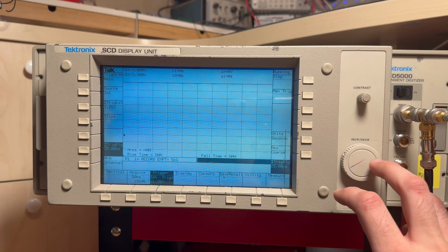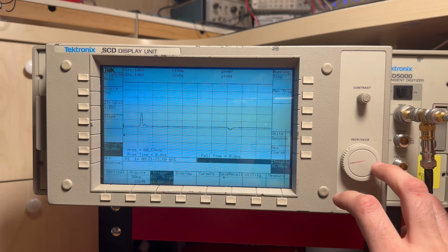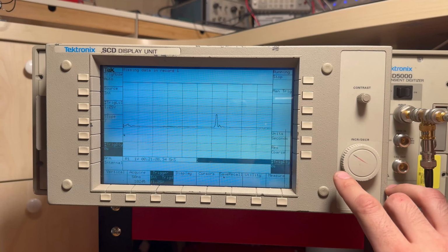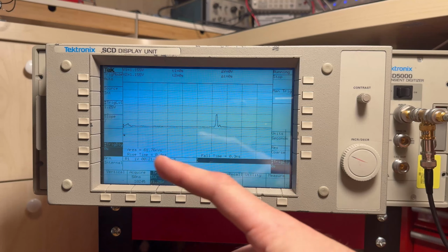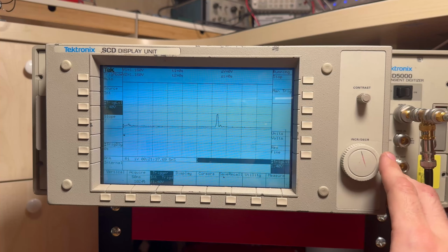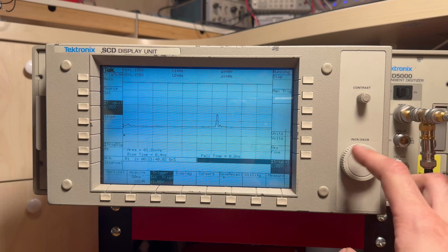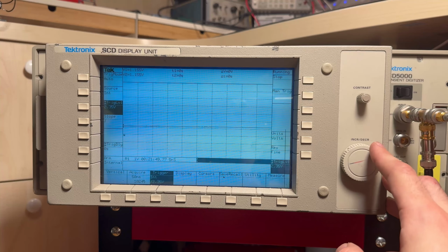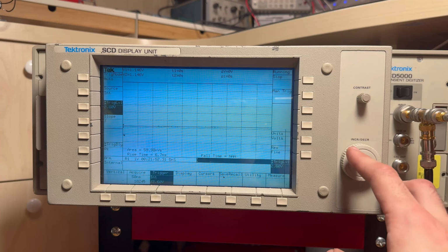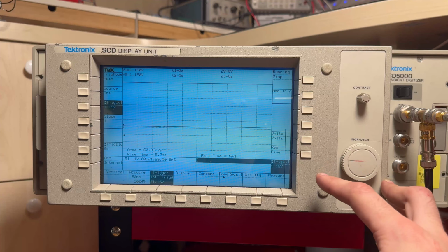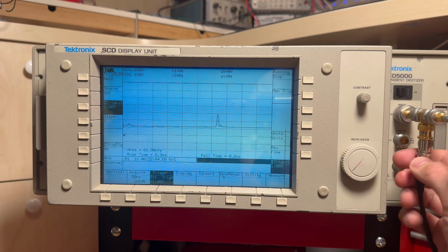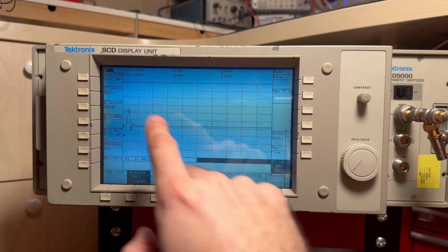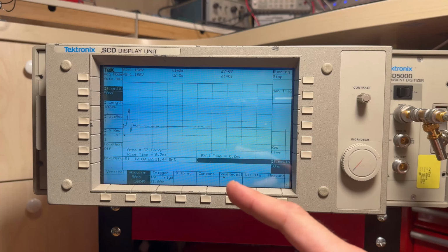because, oh, I don't think it can do that. So our pulse, the incident pulse, is behind. I think I need to lower the trigger level a bit, or increase it rather, so it sees the first pulse and triggers on that one, because now I think it's triggering on the second pulse. I'm not entirely sure. I think this cable is too long. Anyway, it's very, very interesting anyway. So this cable is too long. Let's go back to... Oh, so now it triggers on that one.